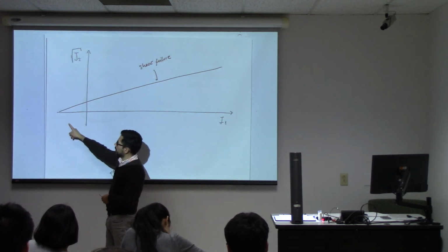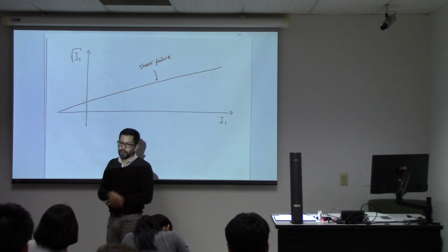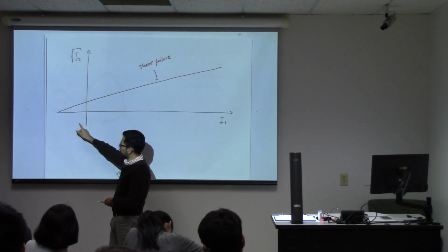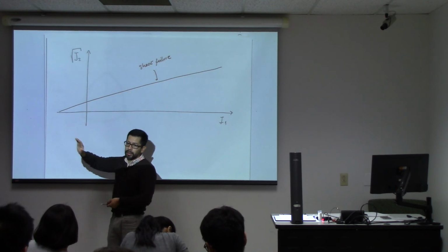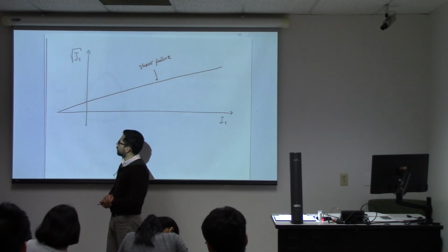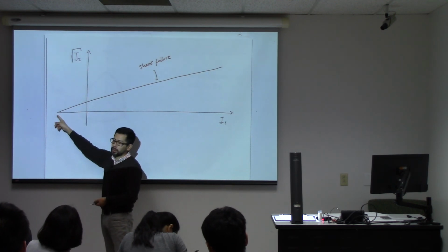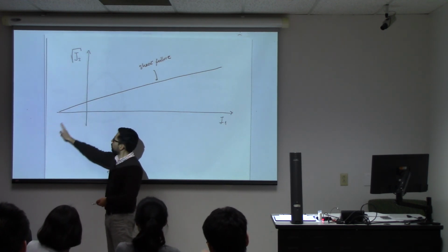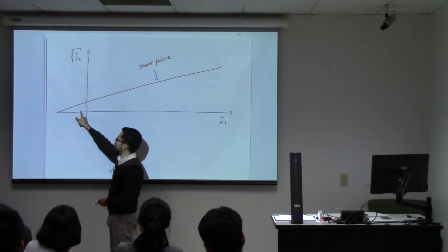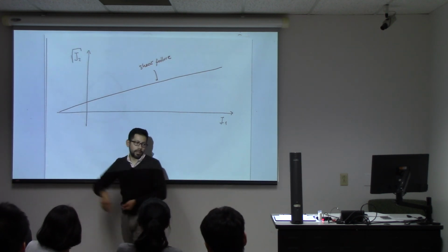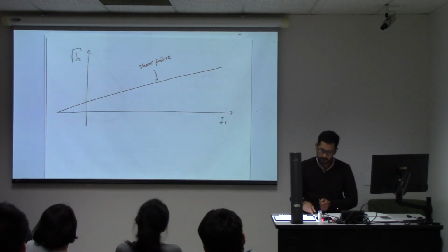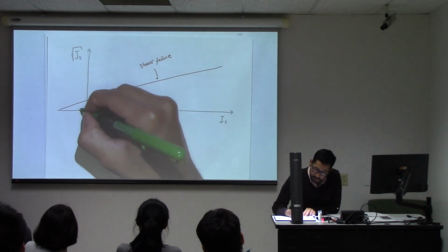Most times, especially with rocks, though with metals it could work well, we see that rocks have a much lower tensile strength than what could be predicted by this line. So this one goes too far. So we need to cut this line somewhere over here. And that value over here is going to be, if I don't have stress in the other two directions, the tensile strength.